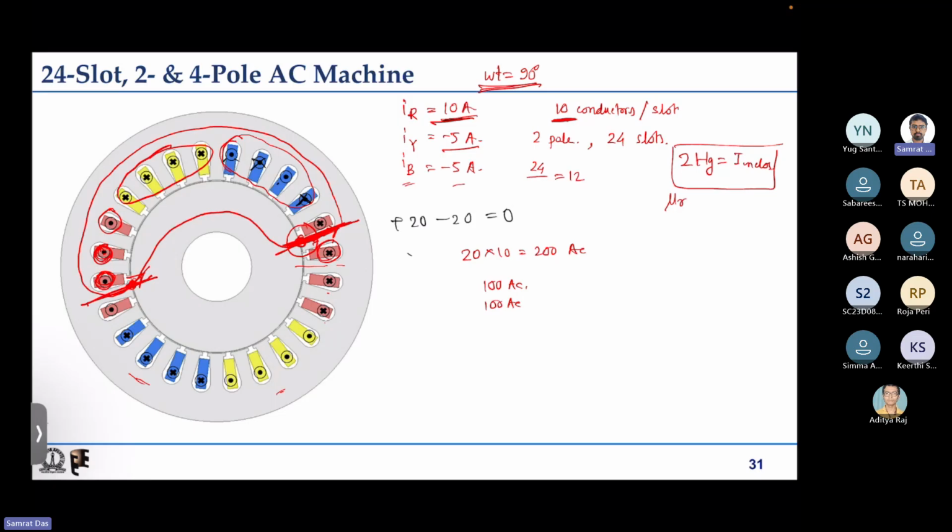Similarly, if we traverse this circumference by taking different loops, it will be possible to show that the mmf distribution that we have in the air gap is a stepped thing which has a significantly high sinusoidal component, and the same thing, H divided by g, that is the H distribution along the circumference, is also the same. And so if we get B, the flux density, that will also have a similar thing.